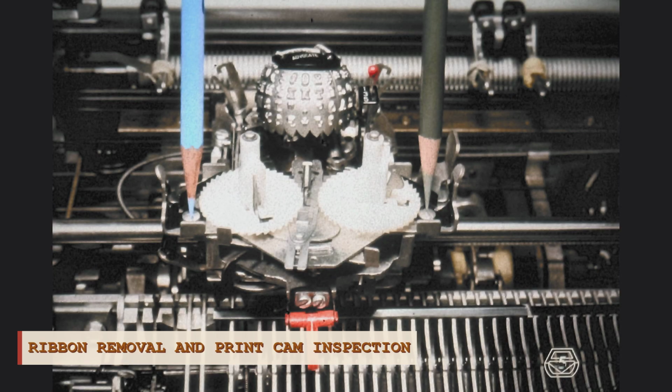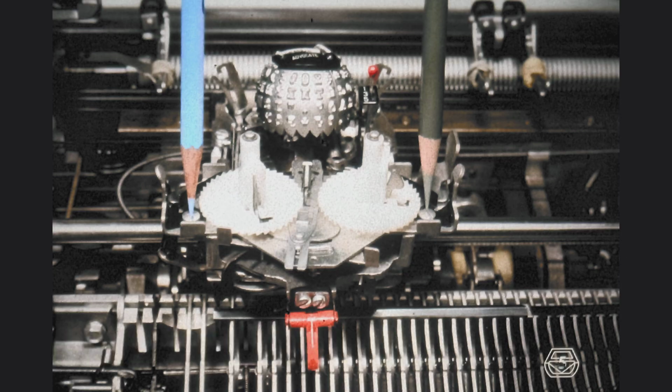In order to see the parts of the printing mechanism we have mentioned, it is best to first remove the ribbon mechanism. If you are using a Selectric II, we recommend that you study training program number 10.5 to familiarize yourself with the removal and reinstallation of the Tech 3 ribbon mechanism and the correcting tape mechanism. For fabric ribbon mechanisms, it will suffice to remove the indicated screws. Be sure not to lose the black retaining springs, which are also held in position by the indicated screws. There is one kind of retaining spring for the right side and one kind for the left side.